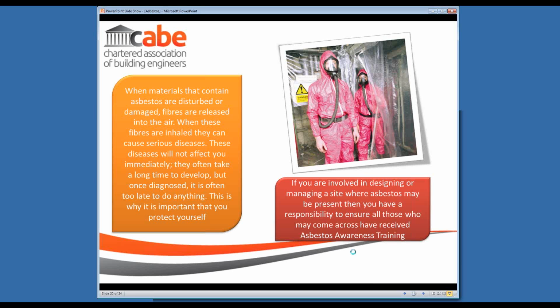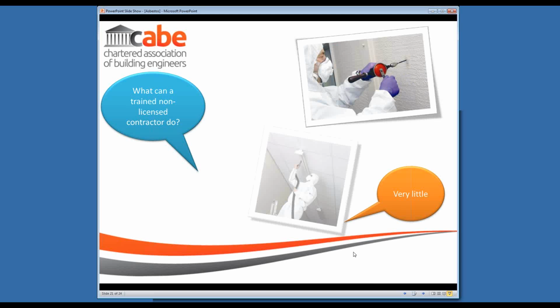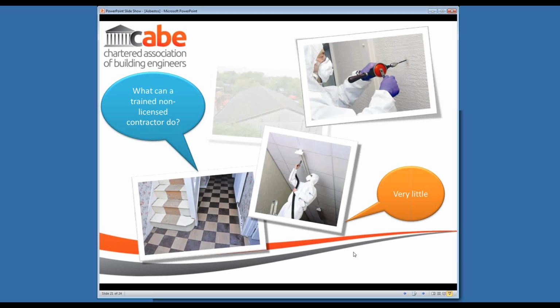Now, as I've said, there is an element of being able to do some non-licensed work, particularly on cement sheets and textured coatings, if the work is of short duration. Generally, short duration is taken as something that's going to last for less than an hour if it's being done by one person, or maybe less than 2 hours if it's a couple of people, but that shouldn't be repeated again within a 7-day period. So it is quite restrictive, but it does allow for the sort of scenario we were talking about earlier with cutting in a light fitting or something of that sort.